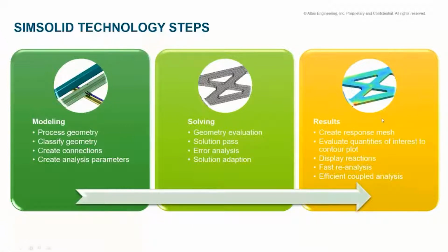So with the results itself, you can always get the same type of results from the analysis that you've implemented, whether you're looking at displacement, stresses or strains, a modal analysis. You can also display the reaction forces and where it's being held. And you can always couple it up with a fast reanalysis. So if you wanted to change a small parameter, you can, and it will solve very quickly. And there's also an efficient coupled analysis. If you wanted to couple up your structural to a thermal analysis inside of SimSolid, you can.